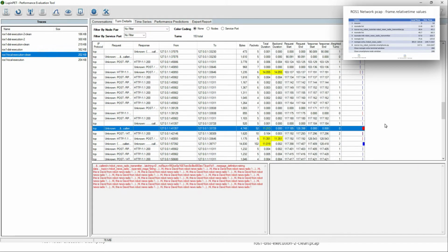So generally when it's in local mode, you see it talking to the ROS master for ROS commands, and when publishers and subscribers first start up to negotiate, identifying them, what they want to do, information about topics and things like that.